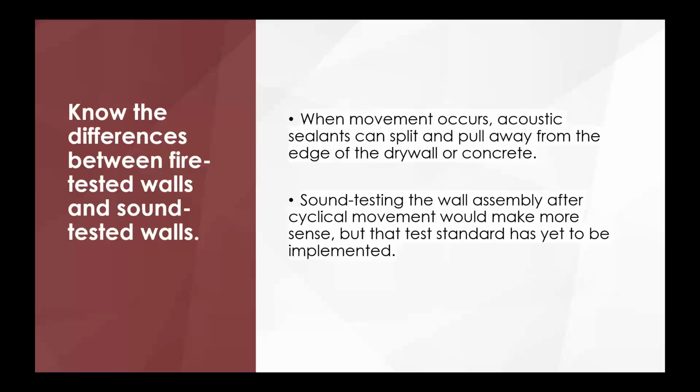If you're on a job and you've got one wall that's a firewall and one wall that's a sound wall, you realize both of them are going to move the same amount. Both of them are going to have that same head of wall movement. So why should they not be tested for head of wall movement? Fire tests are, sound tests should be also.